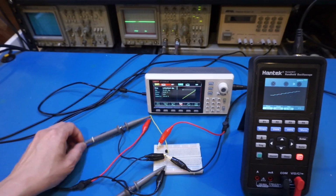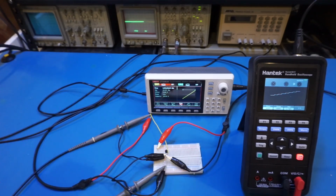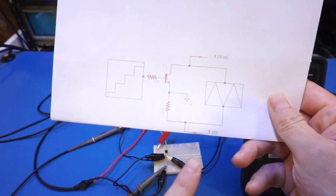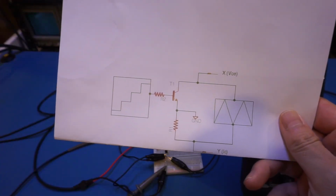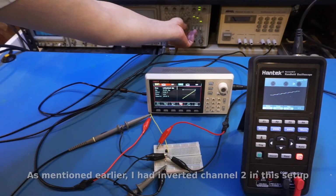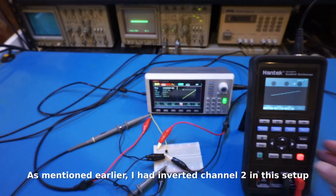And channel 1 is also tied to the collector, so that measures the VCE, whereas channel 2 is connected at the bottom of that resistor R1, as we saw earlier, to monitor the current flowing through the collector and emitter. Now let me turn the scope into XY mode, and we'll enable the output from both of these generators, and we'll see what we got on the scope.